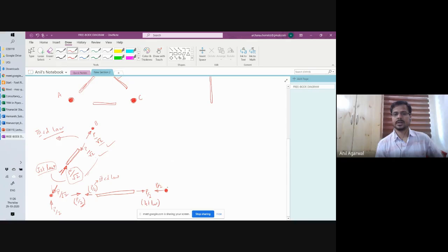And this one could have a vertical reaction, and this one could have a force in this direction, right? So now I know that the horizontal force here is P by 2 on this joint. Sigma Fx has to be 0. That means the horizontal component of this diagonal force has to be P by 2 in this direction. That means this force has to be P by root 2. Okay, so its horizontal component will be P by 2 in the rightward direction. Okay, so P by root 2 here, so its vertical component will be automatically balancing it. So this reaction will be P by 2 again.